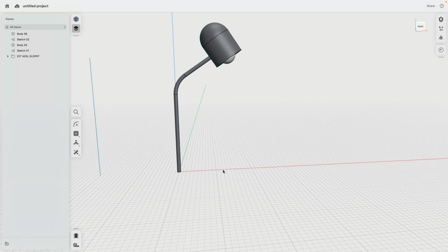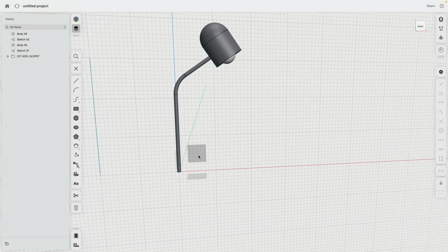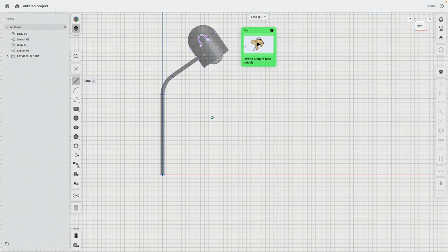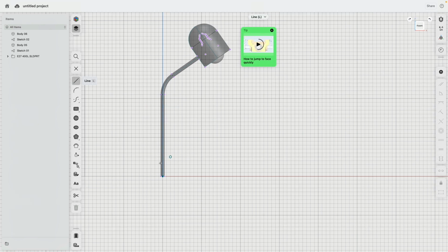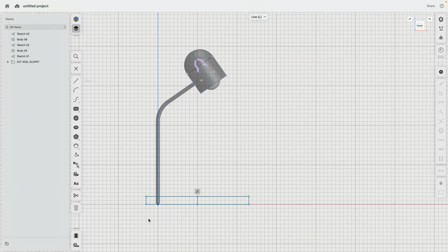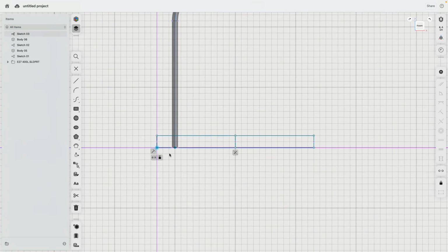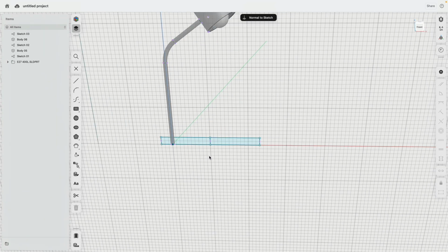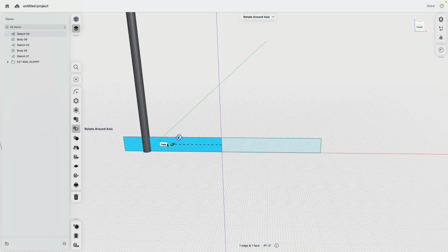Now the gravity will be right under here. So I can go to sketch, but now to the side, and I will design myself a new base. There, and there. One midline, that is important for the revolve command. Then I can specify, well, what is that distance? So 1 inch. Okay, to here.